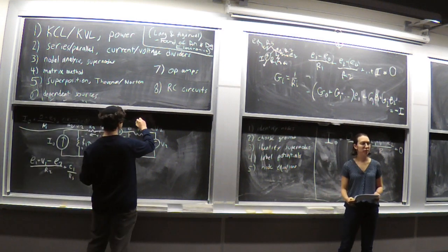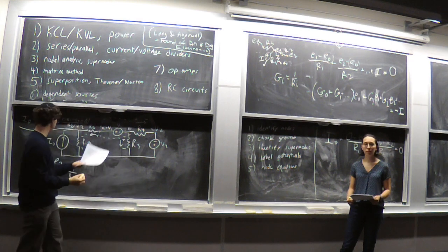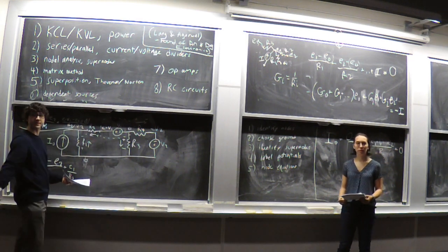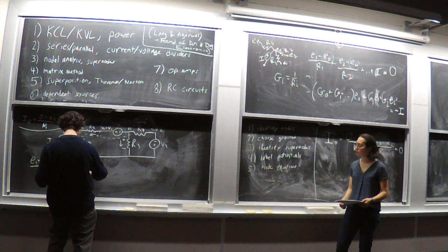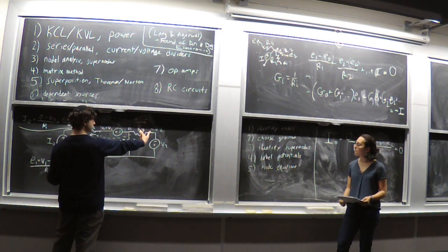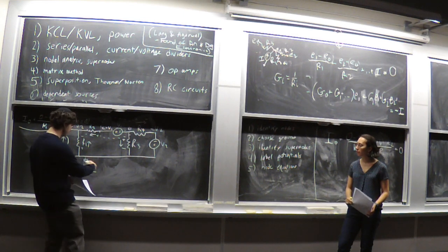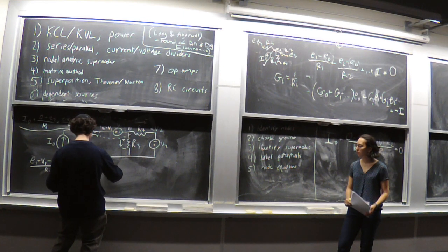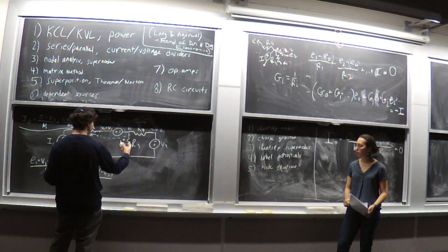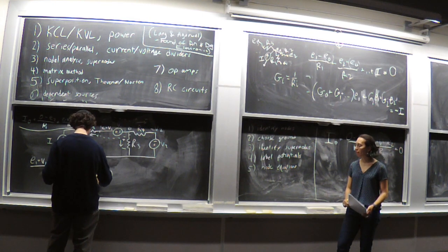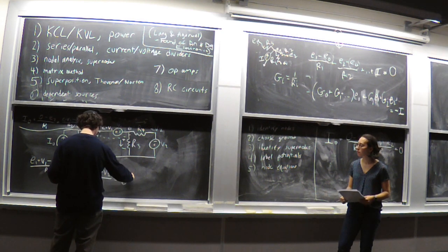Also, we have to be going out, and so, positive and negative, that's also at the E1 side of the supernode. So we're going to have plus E1, and then we have to do minus this voltage. This voltage is negative V2. So we get a minus negative V2, and yes, we can just say plus V2, divided by this resistance R4. And that, too, is going to equal 0.